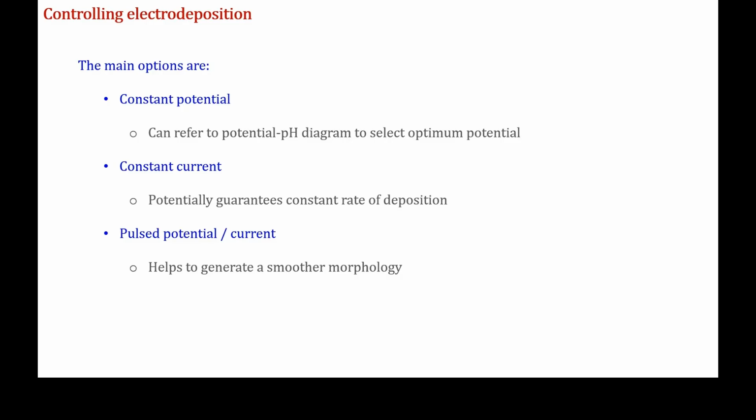But besides the constant conditions, you can do what is done at the Royal Mint, which is pulsing. So in the Royal Mint, the way that they pulse plated their coins, they did it at constant current, but only with intermittent contact between each coin and the current source. Right, so it's kind of pulse plating, but by moving the substrate rather than controlling the current.